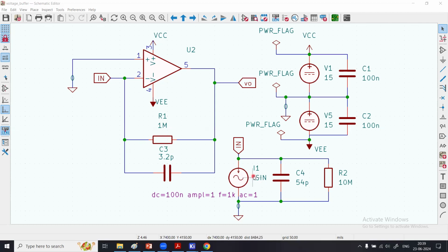So when there is smoke in the chamber, the photodiode, which is represented by this current source, works on the principle of light transduction. So when light falls on it, the photodiode conducts a current, and it works in a reverse bias mode. So it delivers a current as per the light intensity falling on it changes. So when there is enough smoke inside a chamber, light intensity falling on the photodiode will decrease. Accordingly, the current delivered by the photodiode will be modulated.